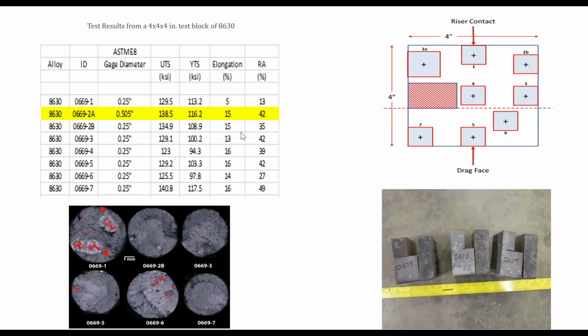That has to do with the fact that in steel castings, our second phase contaminants, whether it's microporosity or inclusions, are on the order of a millimeter. A half inch is 12.5 millimeters, so if it's 1 millimeter, I'm almost 10% of the cross section.